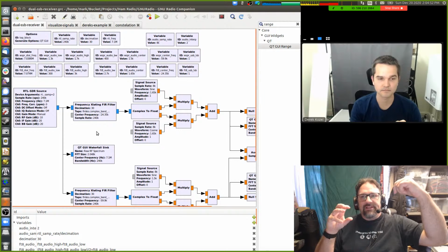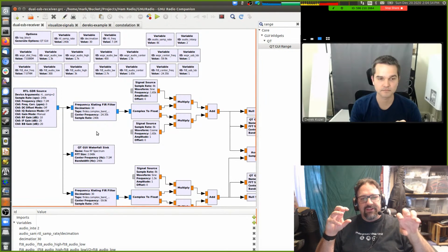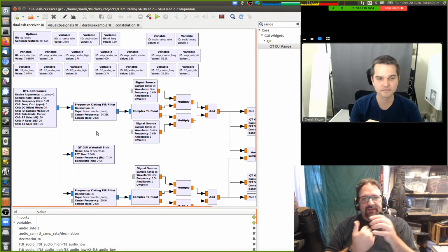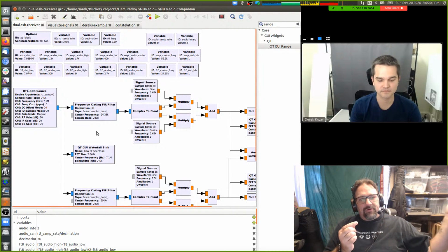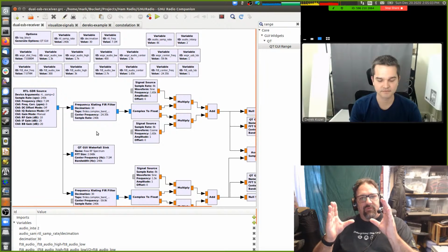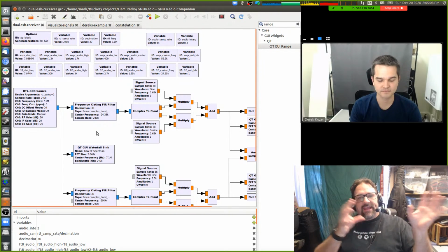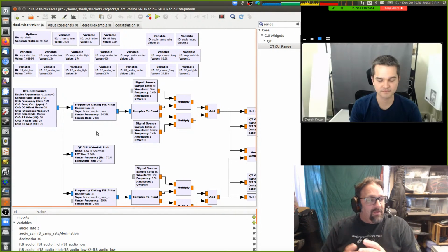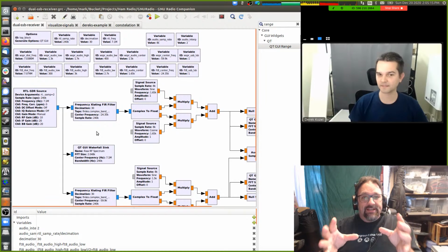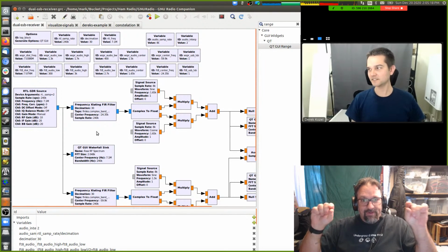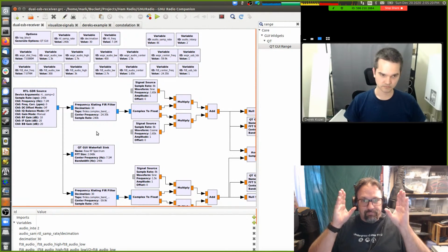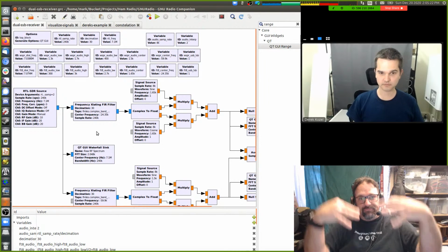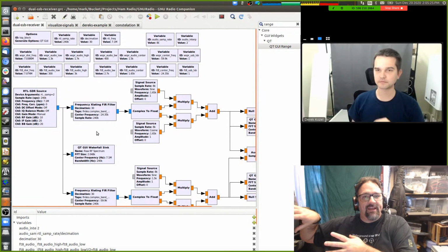I think it's literally just multiplies the constant by the value in each of the positions of the shift register, and then you sum the output of all of those values, and that's your output value. And then you input another sample, it shifts everything down by 1, it does the multiplication again, you sum all of that, that's your output, and you just keep going like this. What is this crazy block doing? Math, amazingness.